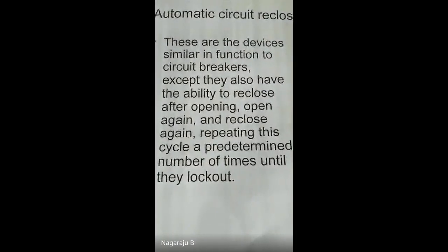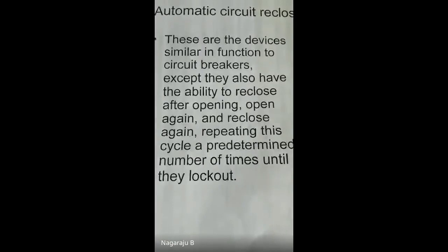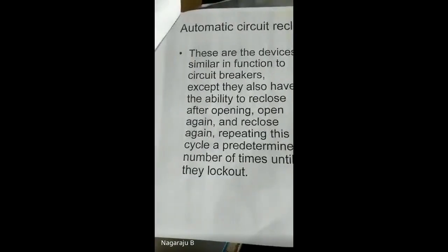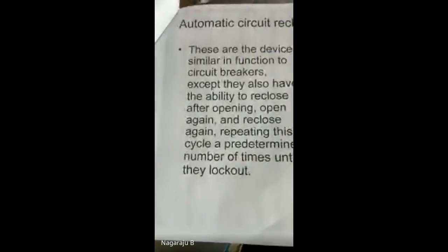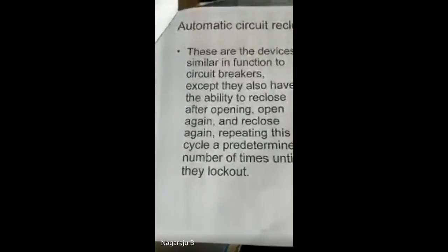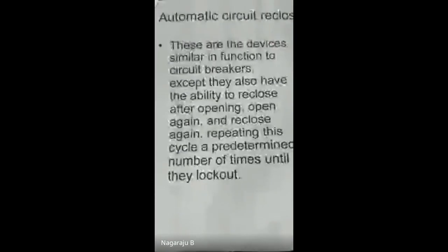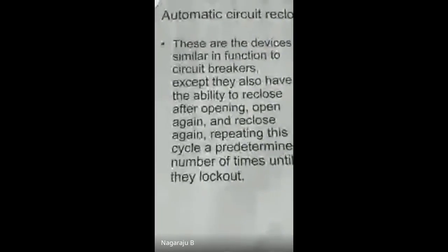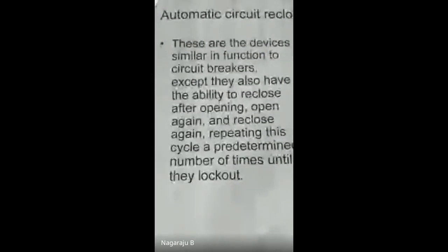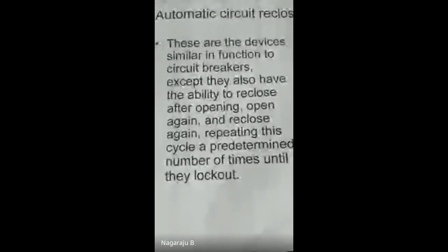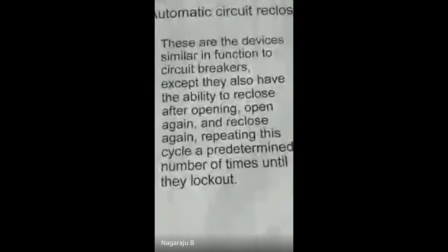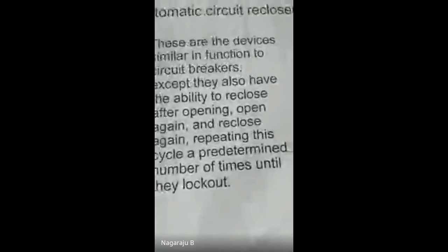These devices function like a circuit breaker, except they also have the ability to reclose after opening, open again and reclose again, repeating this cycle a predetermined number of times until they lock out.